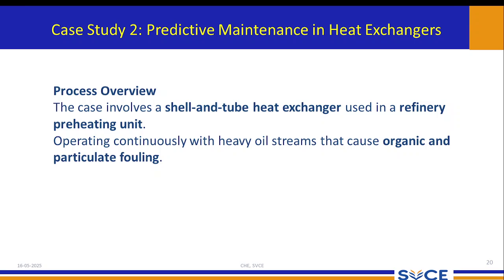So this may occur. As I told you, the fouling liquid will corrode the tube side and things like that. So if you are continuously passing a heavy oil stream, obviously that causes organic and particulate fouling.